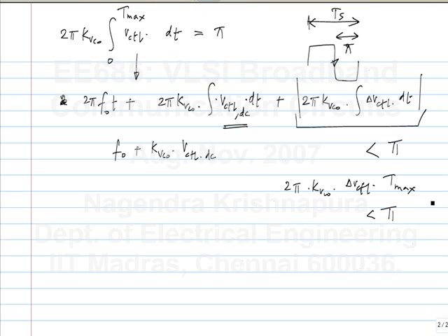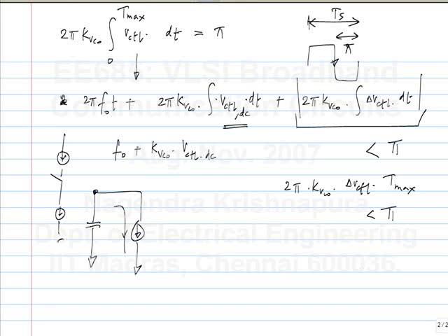Now, in case of leakage, you have a capacitor and you have a leakage current. Let's say you start off with the right value of the control voltage so that it is operating at the free running frequency, but then it starts leaking. If the loop is closed, the negative feedback loop will take care of this. The up and down will contribute some currents such that on average the leakage current is compensated. There will be a phase offset because of this leakage, but it will be compensated for. Now if you break this loop, the voltage will constantly go away from the value that is required.